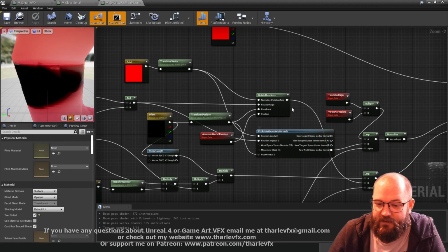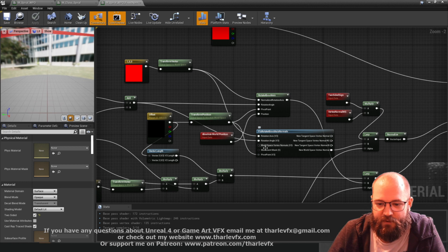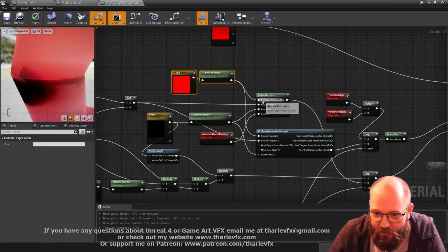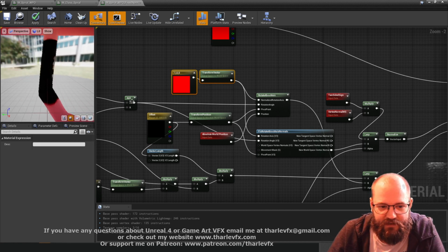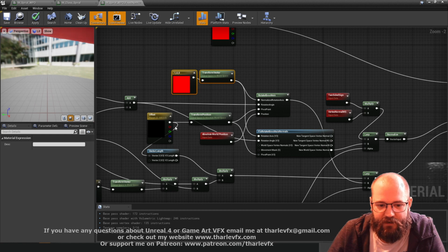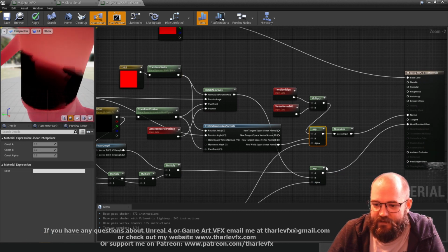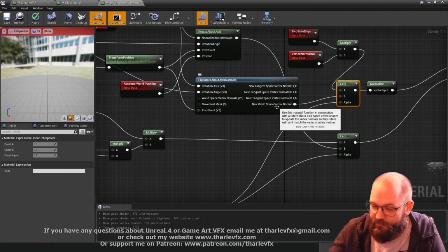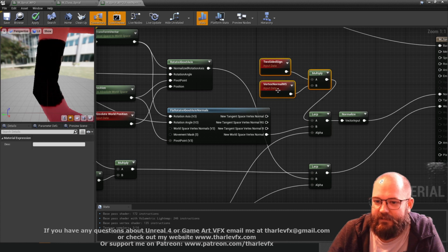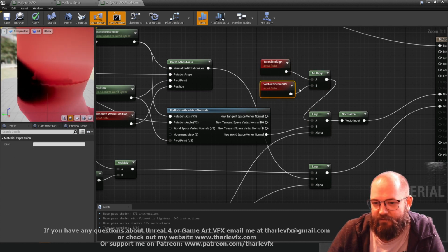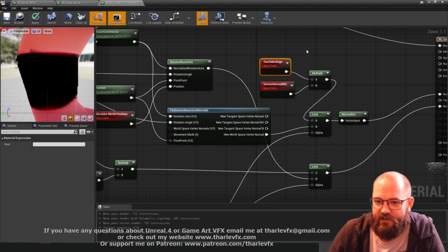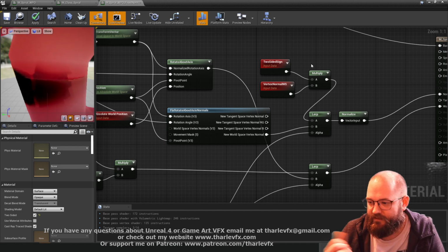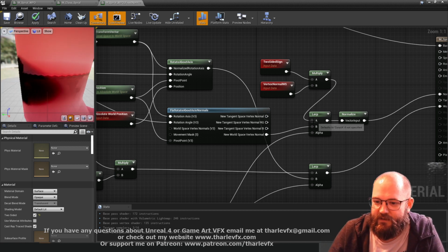And the way this works is very similar to the rotate about axis node. So the same inputs, you can see here: normalized rotation axis is the same, the rotation angle is the same, the pivot point's the same, and all I'm doing is using another lerp, and I'm blending from the fixed rotation normals when I have the spiral, and then the original vertex normals when we have the flat plane. Note, I'm using a two-sided sign here because it's a two-sided material. The vertex normals vary differently on the two sides of the plane, so we're just adjusting those normals.